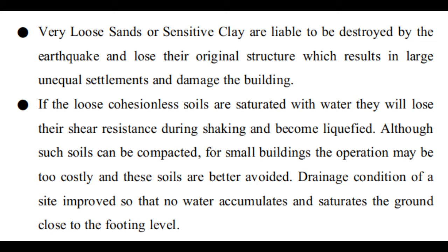So these soils can be compacted, we agree, but for small buildings the operation may be too costly and these soils are better avoided. Correct? Drainage conditions of a site must be improved so that there is no water accumulation and it should not saturate the ground close to the footing level.